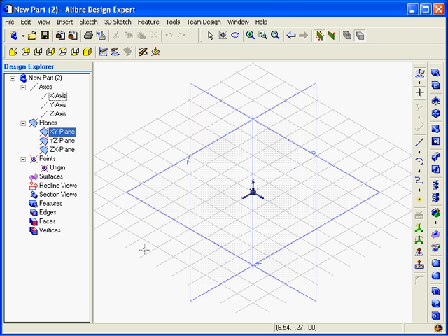When working in 3D Sketch, elevation is also a variable. Coordinate guides are displayed to indicate the location of the cursor. A guide extending from the sketch plane to the cursor indicates the elevation. Notice when I left-click in the workspace, the guidelines are displayed. There is no elevation line because I am currently on the XY plane at 0 elevation.